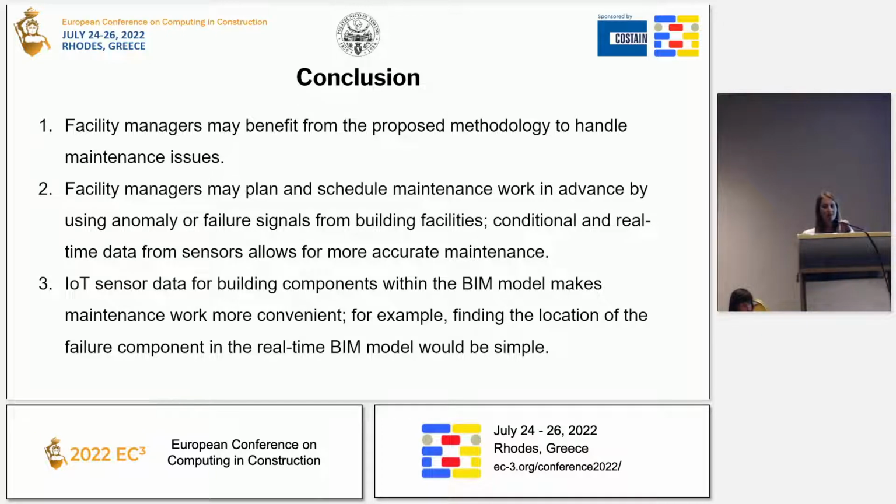This study describes an automated anomaly monitoring and detection method for a single fan coil unit maintenance using IoT technology. The proposed fault detection method was implemented on the application layer and sends alarms to end users or managers when any anomaly happens in order for it to be efficiently repaired. BIM was used to visualize the monitored fan coil unit condition. An experimental case study was used to assess the reliability and applicability of this framework.